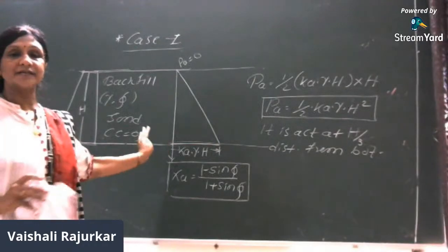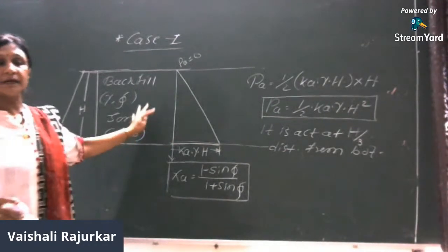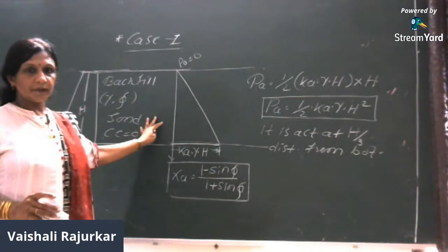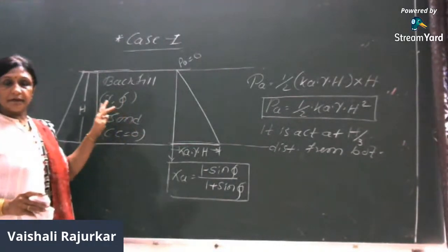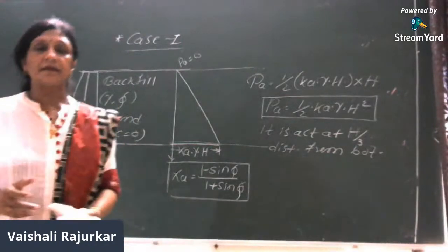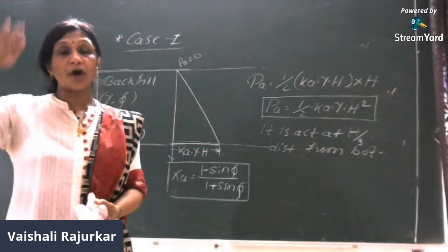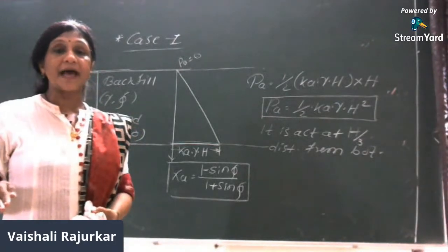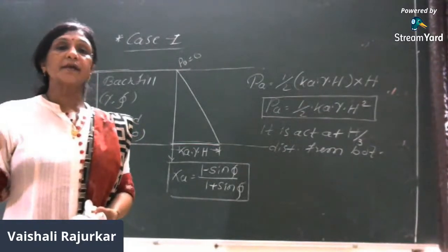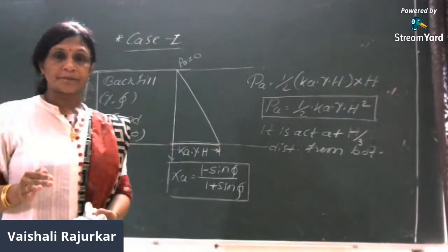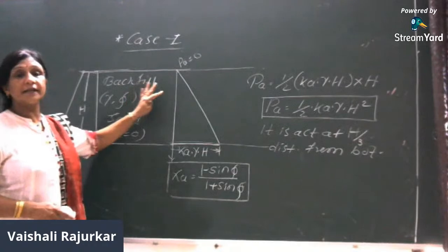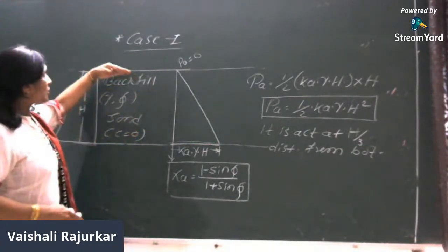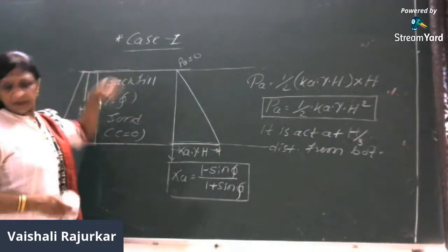That is the critical worst condition, where the water table exists in the backfill zone, right? Therefore, efforts are always taken to remove or lower the water table as early as possible for the economical design of the retaining wall, right? That is the worst condition of the retaining wall, when the soil becomes submerged, meaning the water table reaches the ground level, right?